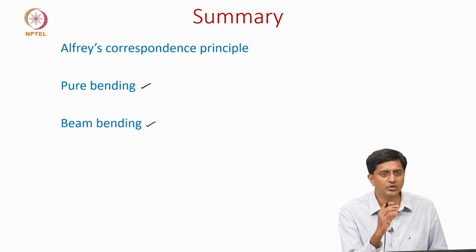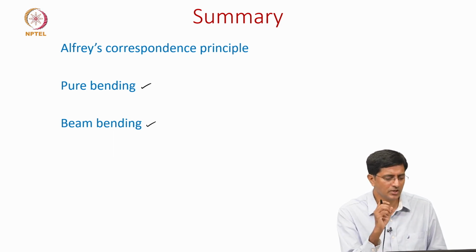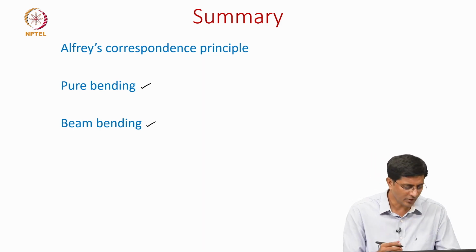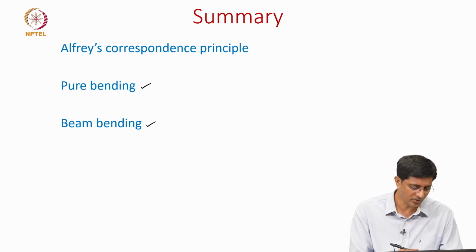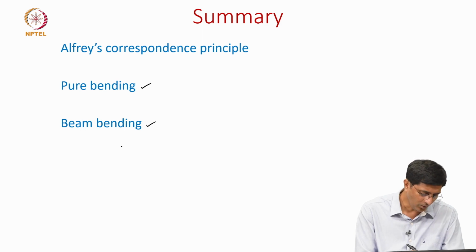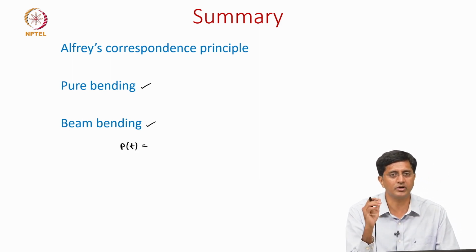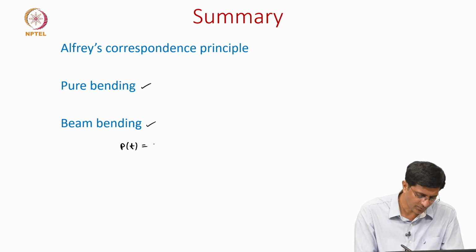Here I need to stress a few things about the applicability of this correspondence principle. We are able to apply it when the load, let us say P of t, is a spatial as well as temporal function, which means the spatial part can be separated as g of x and the time part written as f of t.